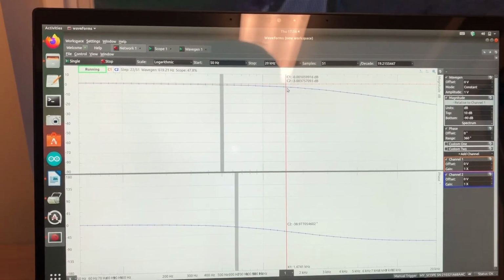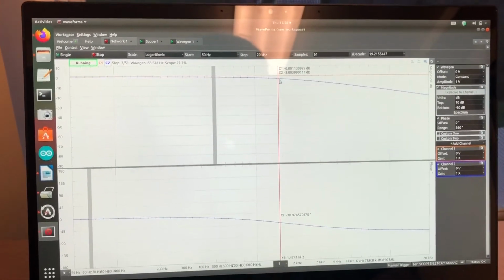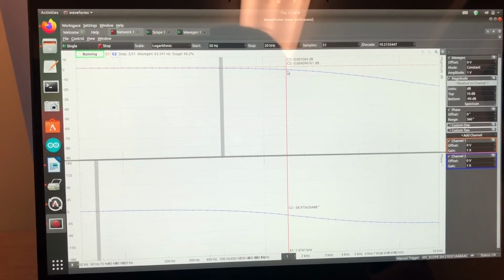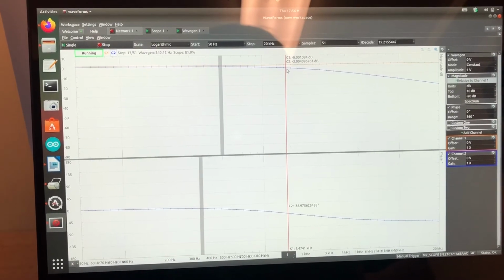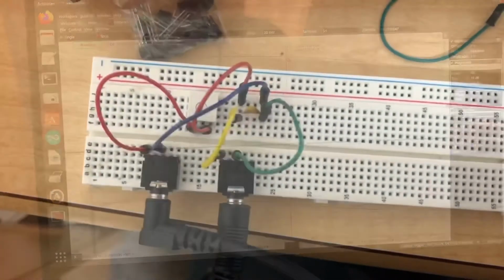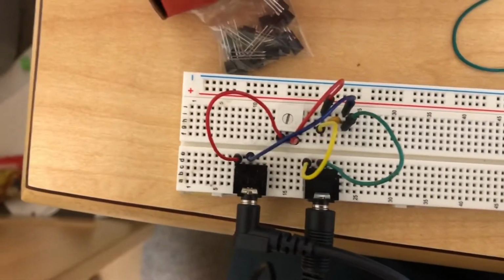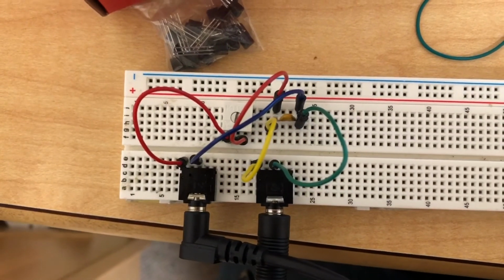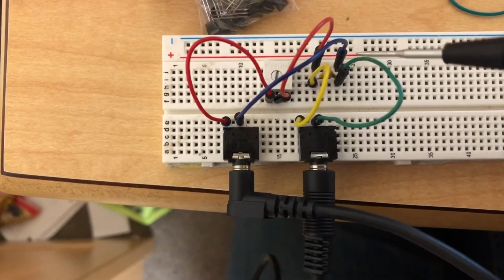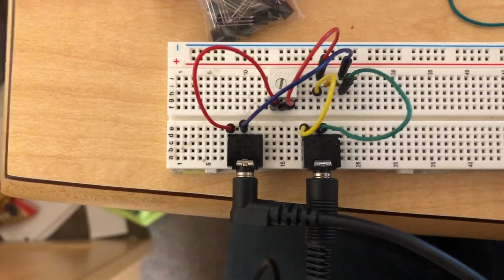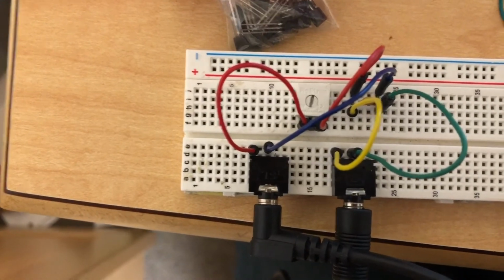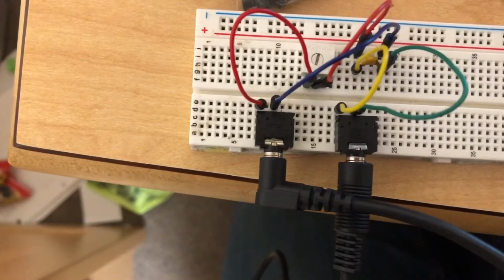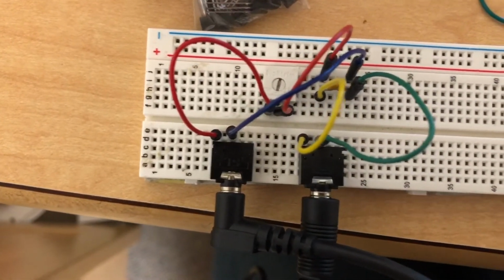Intuitively, that doesn't make a lot of sense. And right now, I'm going to show you what that sounds like when I put some audio through it. And finally, this is the low-pass circuit that I designed. I changed the capacitor value from the 1 nanofarad that I had before to 1 microfarad, and then I changed the resistor to a variable resistor, a 10K potentiometer.